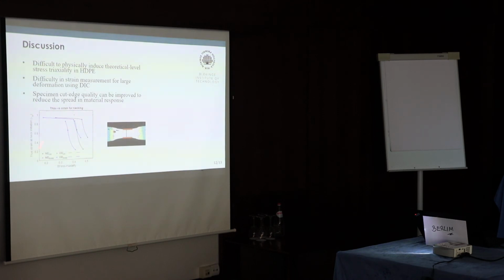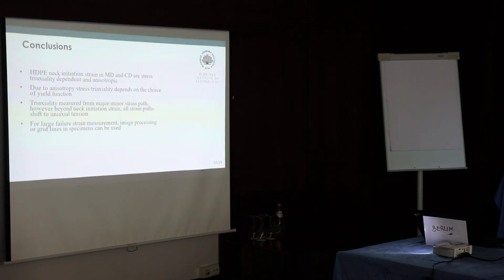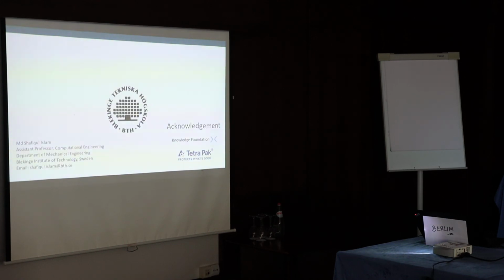We have seen that the stress triaxialities are in a narrow band for machine direction, and an even narrower band for cross direction. So I will conclude that it is dependent, but not highly dependent. Necking initiation could be triaxiality dependent, but for failure, it's quite insensitive to stress triaxiality for this particular material. So thank you very much.